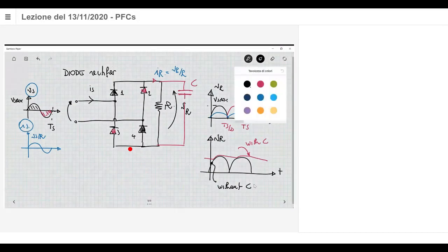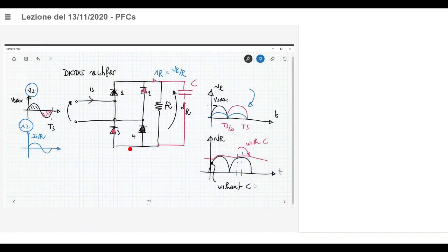The thing that you have to understand in this discussion is that now the diodes conduct over only a very small fraction of the overall period, because the diode now conducts in a small conduction angle, as this is typically called. The diodes are only here to provide charge to the output capacitor, increasing the output voltage level. In all the other time intervals, all the diodes are off. So that means that there is current only due to this small conduction interval.